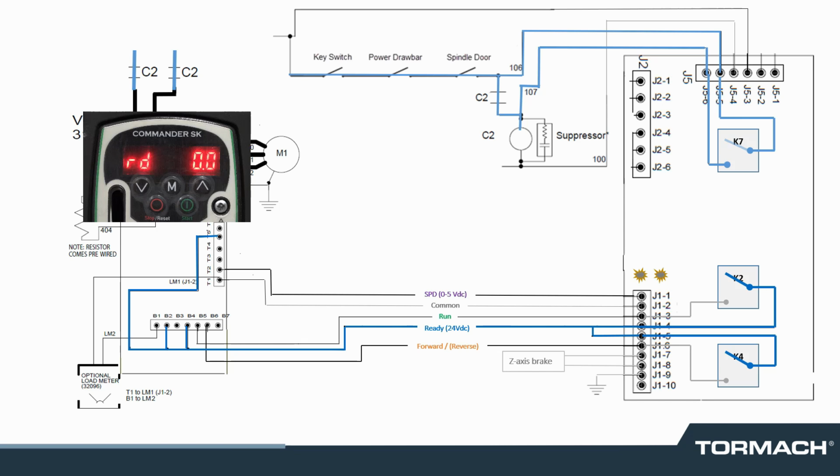The machine control board generates the speed command, a variable signal between 0 and 5 volts DC depending on the spindle speed you desire. Your machine control board has two related indicators, great for diagnostic purposes. A green LED that flashes proportionally to the speed under PathPilot control, and an amber LED whose intensity varies with speed under either manual or PathPilot control.